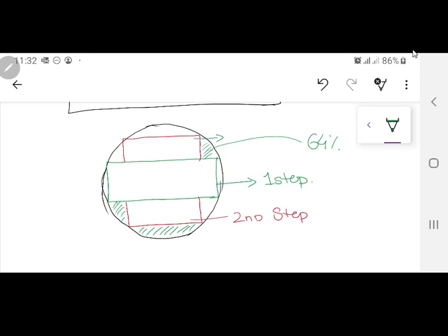Normal practical transformers are designed with 9 or 10 or 11 step cores, and 9 and 11 step cores have a percentage fill area of 98 to 99%. You can't achieve 100% unless you increase the number of steps to infinite. And increasing them to infinite means each and every step has a different lamination, so the cost is also increased, the labor cost is also increased.